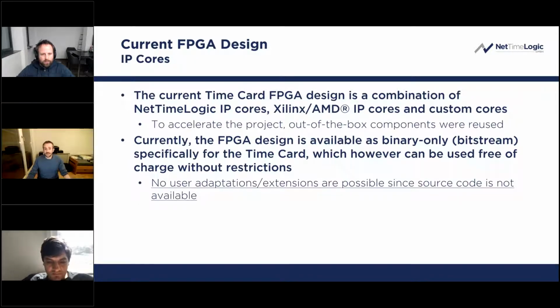This FPGA design is at the moment only available as binary. So this means we provide a bit stream, but this bit stream can be used without any restriction. So you can take the time card, you can load your bit stream, and the design is working. However, this has, of course, some limitation: no user adaptation is possible since the source code is not available. So you cannot put some custom parts into the design and build it for the time card.